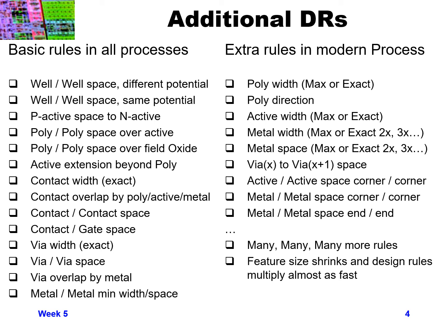For vias, in some cases you might have a requirement for a via on a certain layer and then the via on the next layer above it. So a via between metal 1 and metal 2, and then a via between metal 2 and metal 3. You might not be allowed to have those too close to each other, and there are various different process reasons for that.